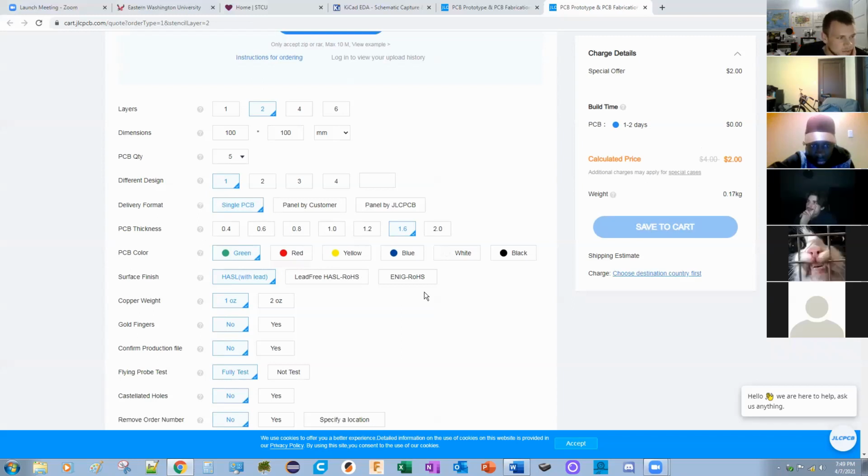At work, we go about it a different way. We got a CNC. It's not really a milling machine per se, but you buy a piece of PCB board, 2-sided, with copper on both sides. Then, using these itty bitty tiny bits, you drill out around the trace just enough to go through the copper, so you almost mill your circuit out of a piece of copper.